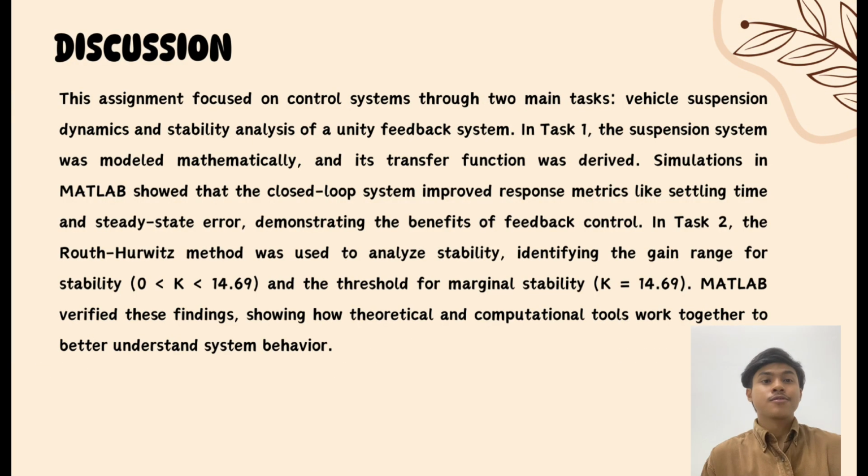So basically, this assignment is focused on control systems through two main tasks. First is vehicle suspension, dynamics and stability analysis of a unity feedback system. In this task 1, the suspension system was modeled mathematically and its transfer functions were derived. Simulations in MATLAB show the closed loop system improves response metrics like settling time and steady state error, demonstrating the benefits of feedback control.